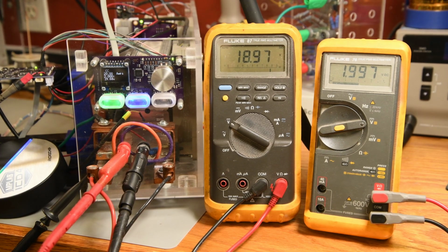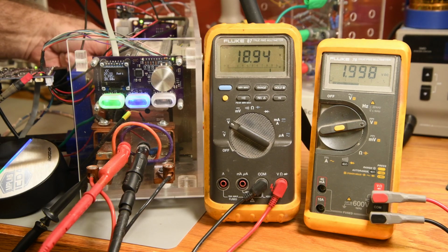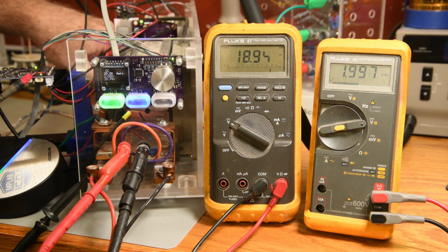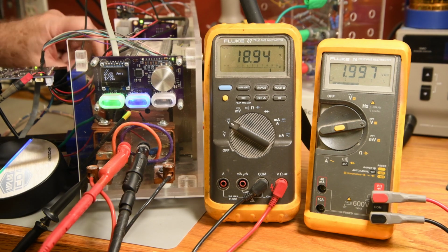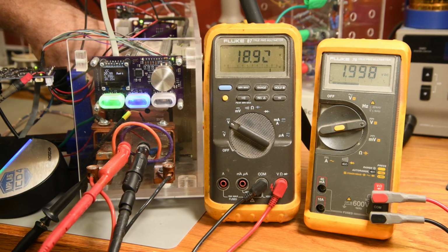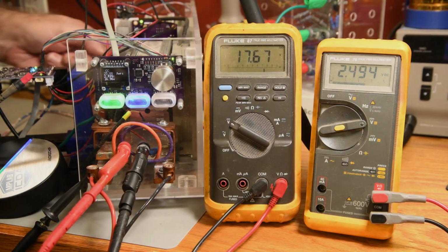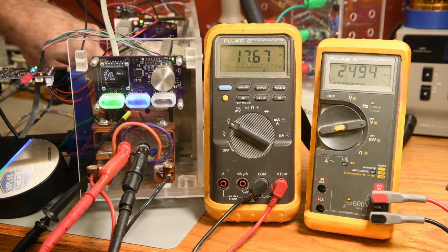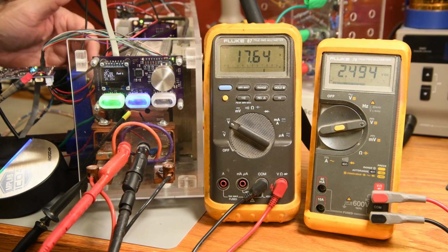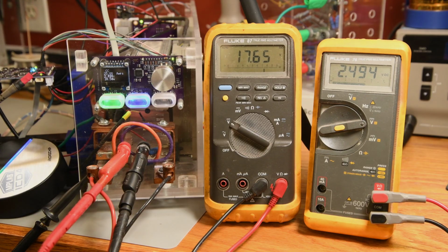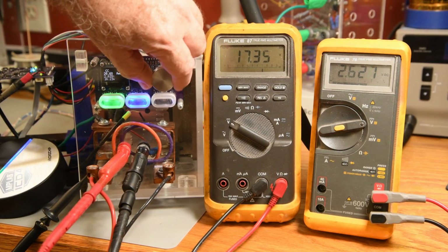Getting close to 400 watts here, and the air is feeling warm coming off the fans. Power transistors aren't that hot though. I can keep a finger on the leads. They're hot, but really cooler than I would expect. I was going to stop at 25 amps, getting close to 450 watts, but nothing is feeling overly hot. I'll push it a bit harder.